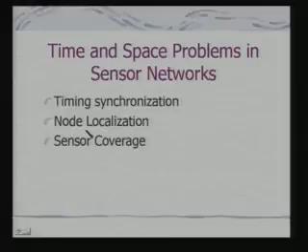Obviously, the other problem is that of node localization. If a node A has detected a target moving out of its sphere of influence, it should realize in which direction it is moving out. So, it would localize the direction in which the target is moving out, and along with it, it should localize itself in the sensor net in the context of its neighbors, because it has to identify an appropriate neighbor and inform the neighbor to track the phenomena.